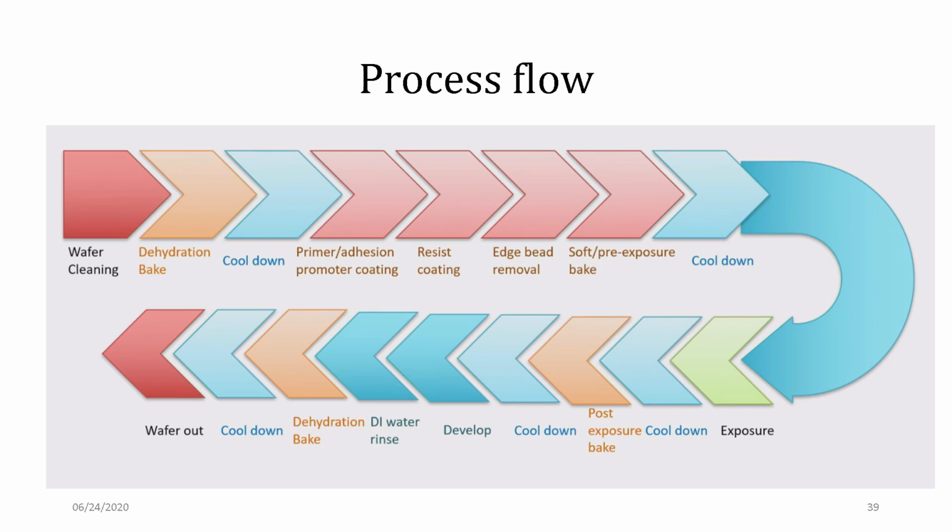We have a resist, which is a photosensitive polymer, and it has to be spin coated. The spin coating determines how uniform it is. You need to make sure that it is very uniform and does not spill over the sides, and that it is spread across the entire substrate uniformly. Once it is coated, we need to soft bake it, which means that before exposure it has to be slightly baked, then cooled, and then exposed to the UV light that we are talking about. Again it has to be cooled down. Then it goes through another exposure. After exposure, it has to go through another baking. After that, it has to be cooled.